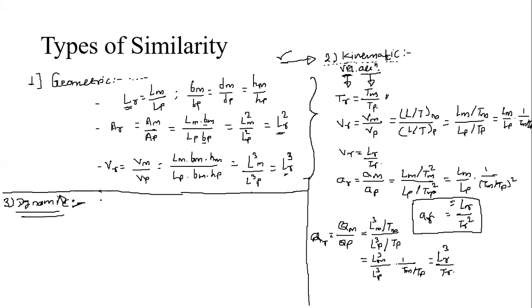So I'd like to write in that language of the momentum itself. Momentum, that is a mass into velocity in a model divided by momentum in a prototype of a flowing fluid at a particular points or at a particular locations must be the same one. Then and only then we can say that there exists a dynamic similarity. That is completely done, that is, summarizing is done.